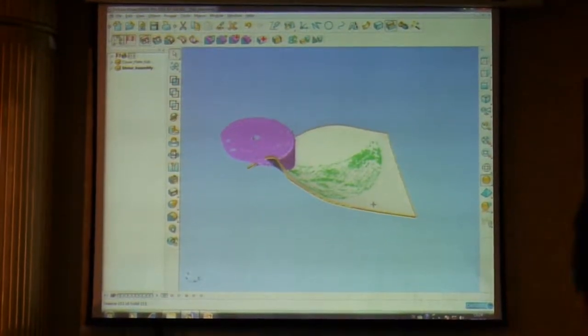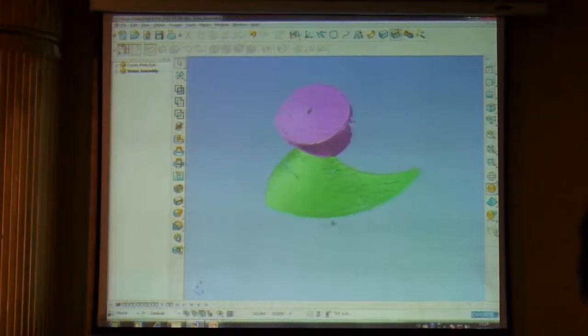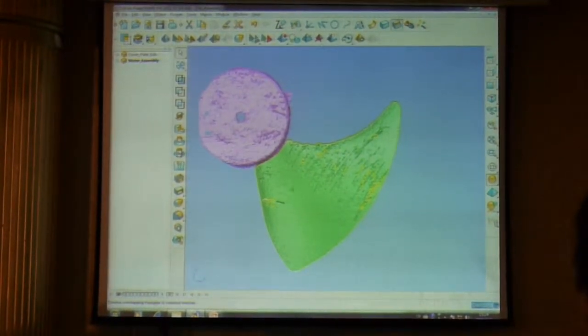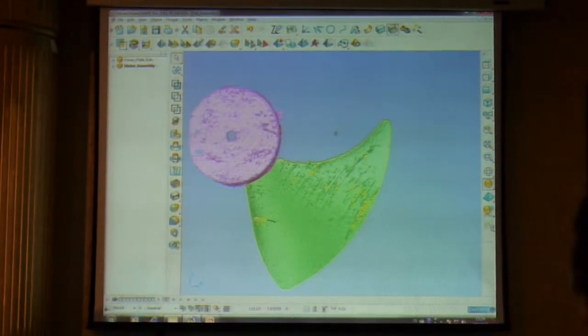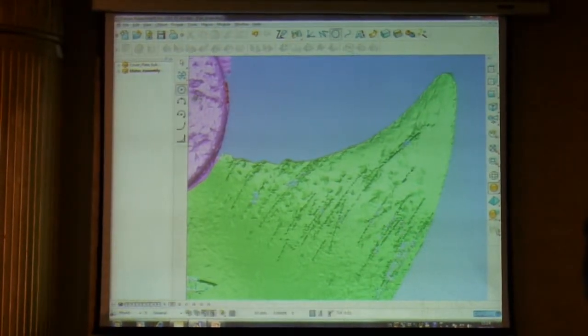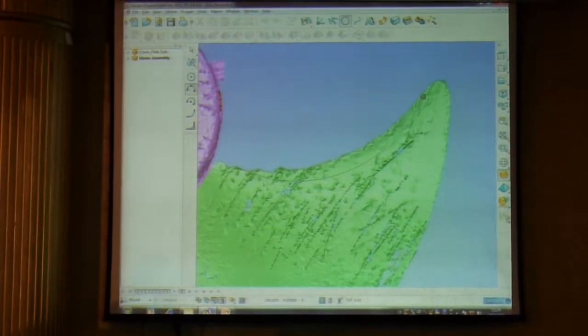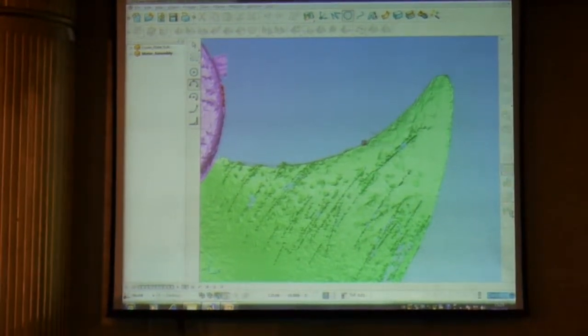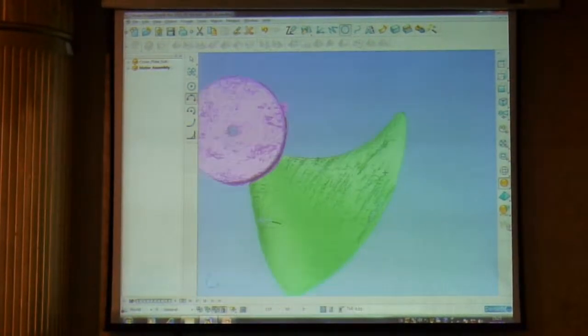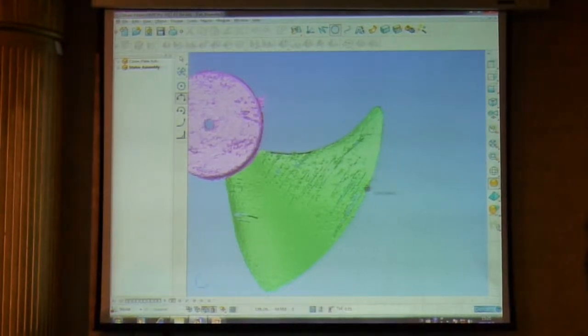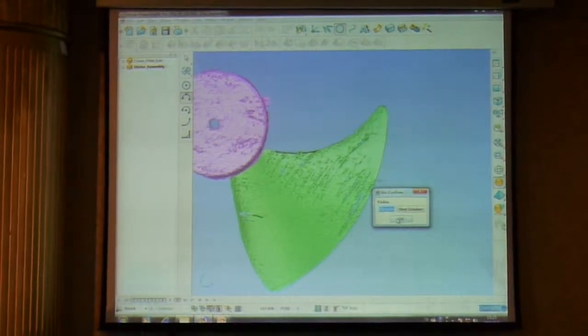Okay, let me just hide the smooth surface for one moment, and again look at the blade profile. So the next thing we have to do is to capture the outer edge shape of the blade that we're constructing. So I can now use PowerShape's geometry construction tools, so we can construct lines, arcs and curves, and I can simply touch on the edge of the triangle data, and in this case construct curves.